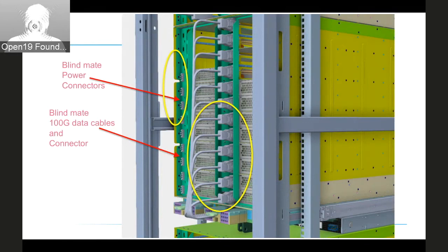Each one of those connectors represents 100 gigabits per second today at 25 gig signaling, and 200 gig capable at 50 gig signaling. It's pre-designed and pre-tested for 200 gig per server, which we believe will take it a while to be exhausted. On the power side, we enabled 400 watts for every brick, which means every half-width 1 RU server will get an entry level of 400 watts, and it will scale with size.